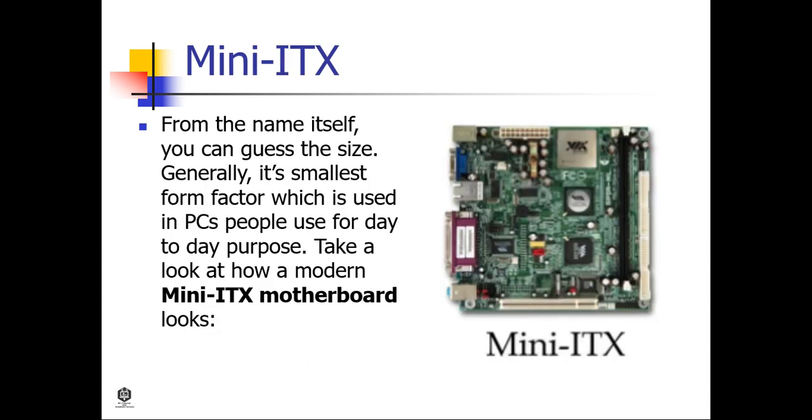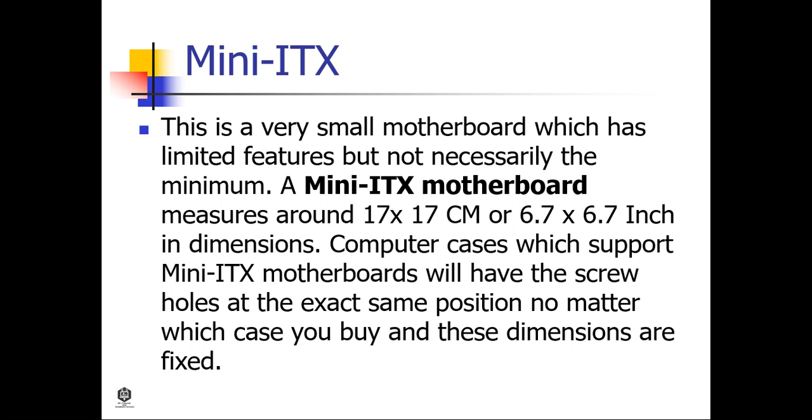Next, the Mini-ITX. From the name itself, you can guess the size. Generally, it is the smallest form factor used in PCs for day-to-day purposes. Take a look at how a modern Mini-ITX motherboard looks. This is a very small motherboard which has limited features but not necessarily the minimum. A Mini-ITX motherboard measures around 17 by 17 centimeters or 6.7 by 6.7 inches. Computer cases which support Mini-ITX motherboards will have the screw holes at the exact same position no matter which case you buy, and these dimensions are fixed.